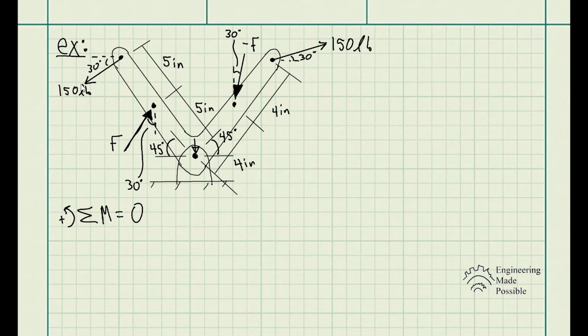So let's go ahead and analyze the first force, being the 150 pounds of force, that has a 30-degree angle with respect to the horizontal axis. So the thing is, split it to its x and y components. So we have the y component going downward here and the x being this portion. So it's nothing more than trig to solve for the component.